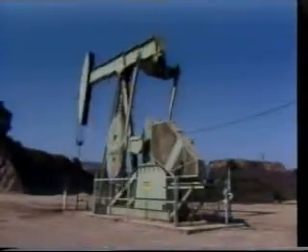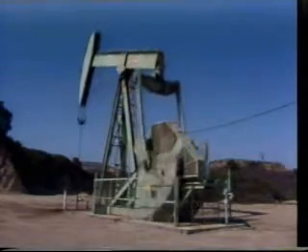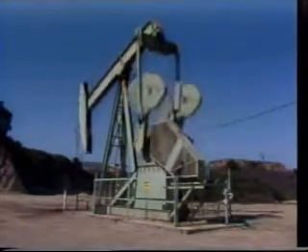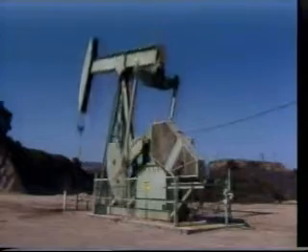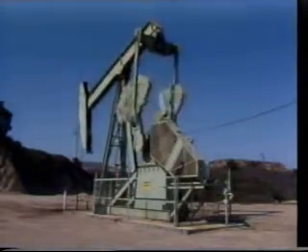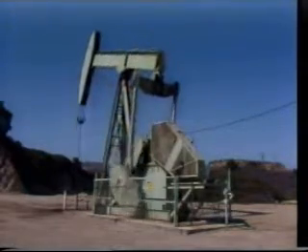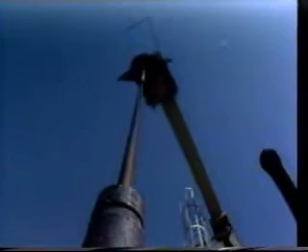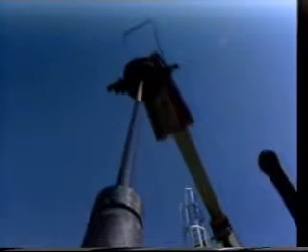If the bottom hole pressure of a well becomes so low that the well will no longer produce at a desired flow rate, or perhaps at any flow rate, some sort of artificial energy supply is needed to help lift the fluids out of the well bore. Energy can be supplied indirectly to our well by injecting water or gas into the reservoir to maintain reservoir pressure, or directly through a variety of artificial lift methods which are applied at the producing well itself.